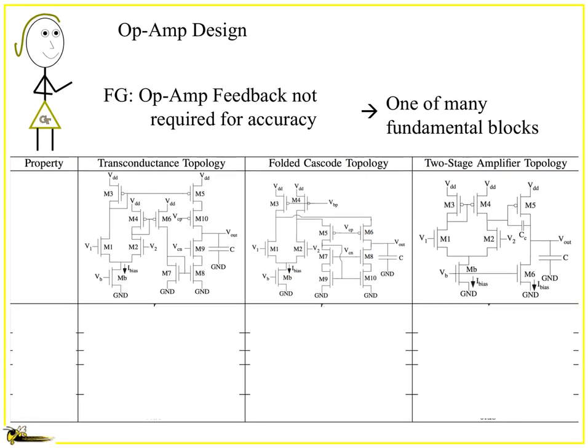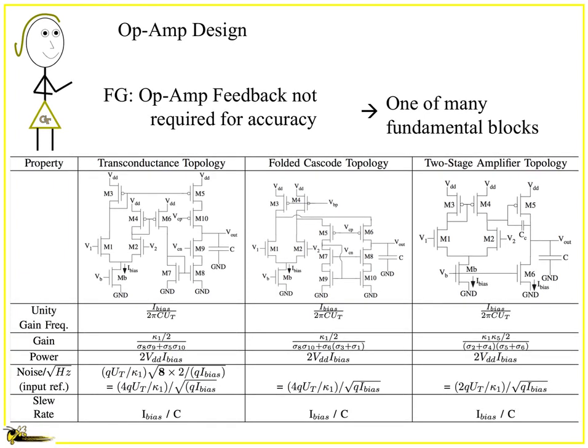Here's what's interesting. If you look at the parameters in all 3 cases, you get very similar parameters in any of them. And so it's really a question of artistic design which you'd want to do. Probably the transconductance amplifier and the folded cascode are in general easier ones to design, easier ones to replicate and do in many places, with the fewest amount of parasitic craziness that can happen. But you can get away with only probably a couple different topologies, and that's sufficient for a fully configurable structure, particularly with a programmable bias current.